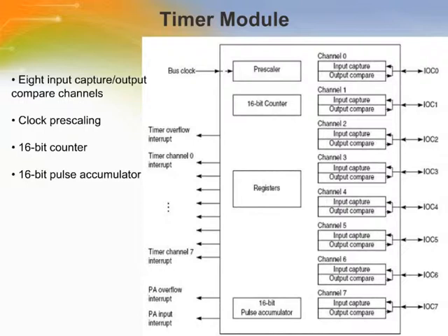The basic timer consists of a 16-bit software programmable counter driven by an enhanced programmable prescaler. This timer can be used for many purposes, including input waveform measurements while simultaneously generating an output waveform. Pulse widths can vary from microseconds to milliseconds.